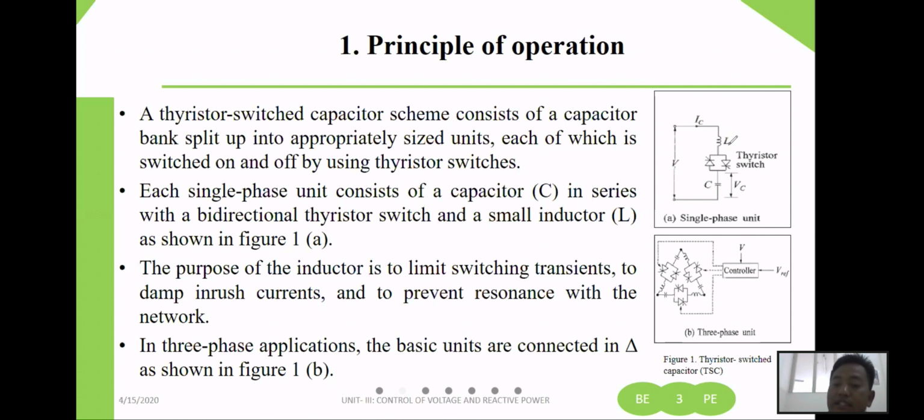Here we have assumed that the capacitor voltage and the bus voltage have the same polarity, and at the same time the bus voltage is maximum. Why we are doing this is to ensure transient free switching. If you choose T1 in some other way, it will still function, but you will face a transient switching problem.